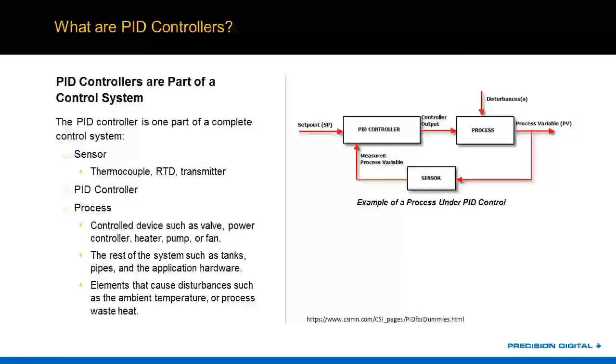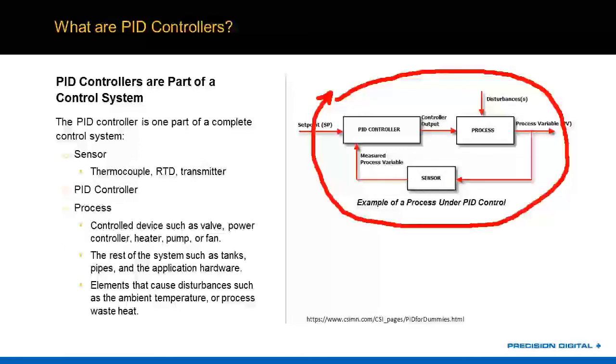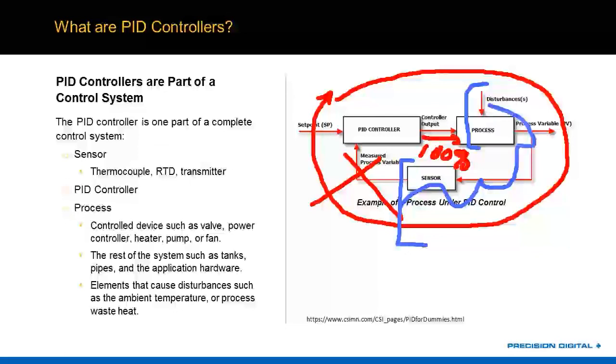Here we go. That talked about that single loop, right? The controller gives an output which changes the process, which you measure and bring back into the controller. Well, a loop break alarm says, hey, look, I have had my control output at 100% now for some time. And yet despite that, I am not seeing any change to my measured value. So something in this process, something between my output and what that sensor is reading, something over in this area is broken, and I should set an alarm off because this just doesn't make any sense.